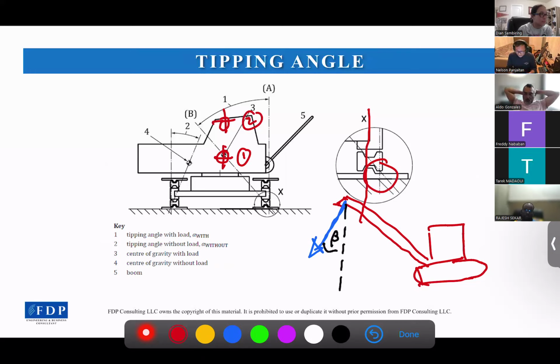Now the question is, why is it not allowed? Does anyone know what the reason is? Because the crane is for lifting, but not for pulling. So in that case, this angle is pulling. This is not what the manufacturer says, but good practice. The meaning is we need to work within less than 5 degrees. Correct, that's the practical saying.